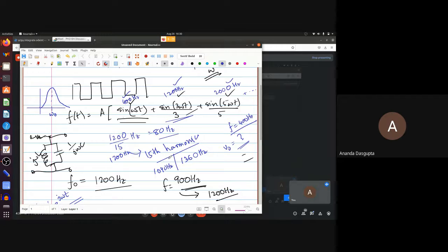So what you will see is actually almost a 1200 hertz sinusoid, but with 1360 hertz slightly and 1040 hertz slightly mixed in. So what you will see is not a sinusoid. I will not even try to draw it, but you will see something like peaks and troughs in the sinusoid. Standard beats which come in when you have frequencies which are close by superposed. So for higher harmonics, that is, when your input frequency is low and you are only getting resonance from very high harmonics, the nearby harmonics are not far enough away to be suppressed completely. So you will get an output.